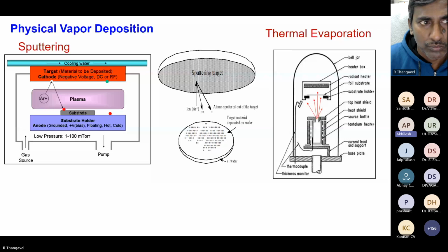Now interconnect. Basically, two types of interconnect: the aluminum interconnect or the copper interconnect. Copper has an excellent electromigration reliability and 40% lower resistance than aluminum.